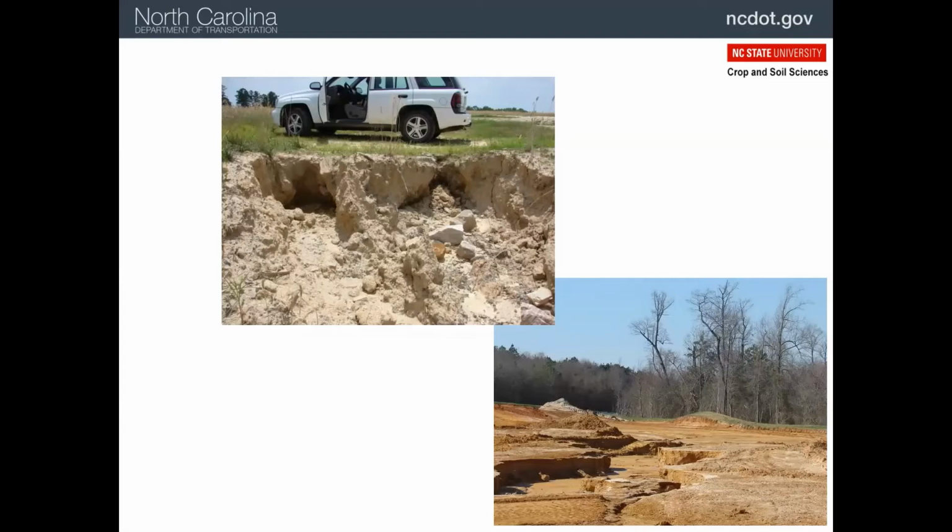So you look over here and you'll see all that pile of soil. Well, that caved in. So now the water's going to come along in this waterfall, wash all that out, and start this process all over again, and then it'll cave in. And as a result, you can get a lot of erosion, a lot of sediment moved out. And so you really don't want to ever see gullies like this on a site. This is a mismanagement evidence right here.